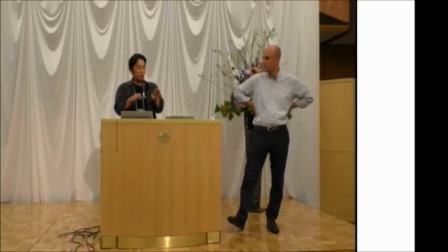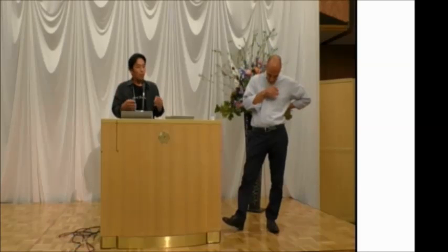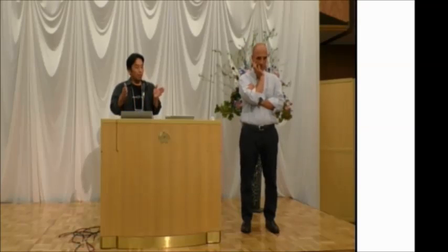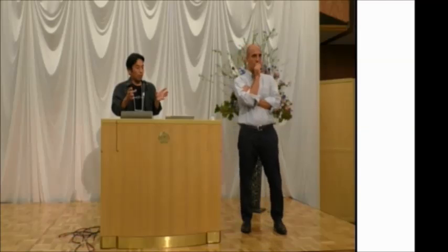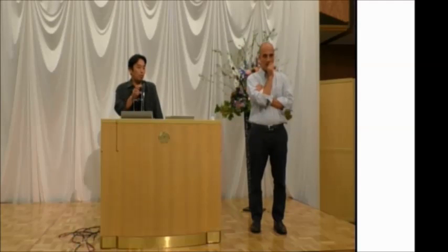For example, to reproduce the braided channel, if we use a three-dimensional model, maybe we cannot produce the braided channel, so it takes a very long time. For alternate bars or a very simple braided channel, maybe a two-dimensional model must work very well.